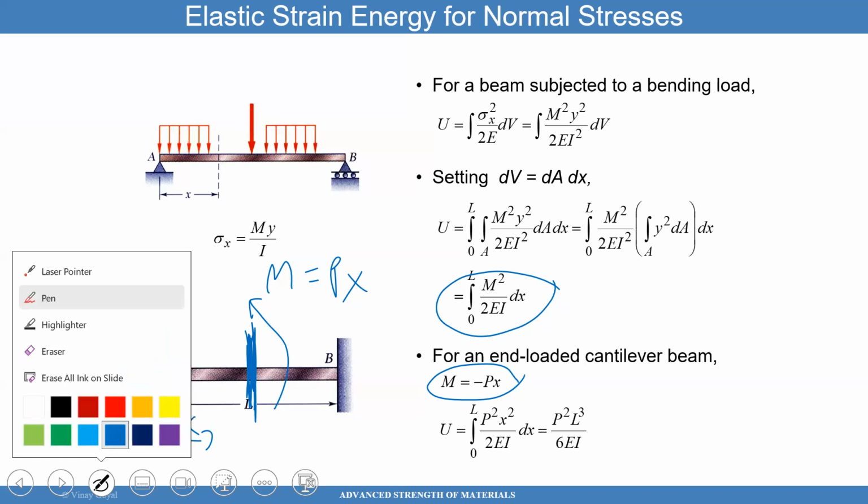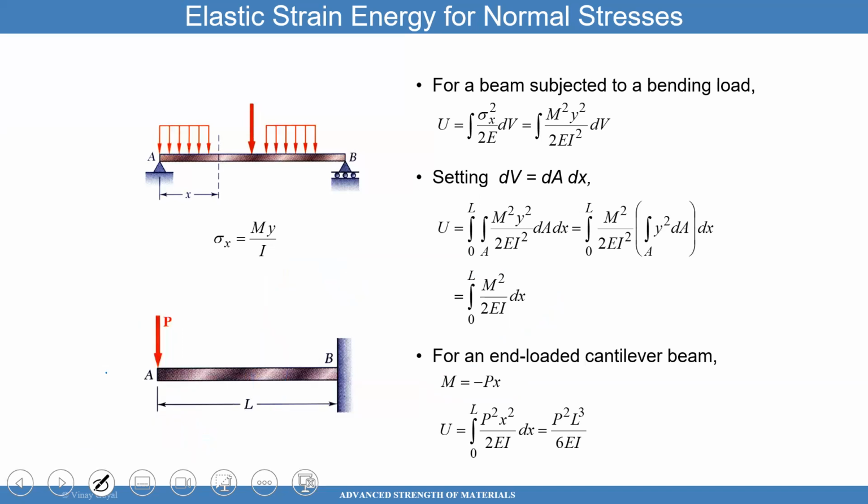And moreover, and I'll cover this later, but just for fun, this is equal. What is the work done by this load applied? 1/2, 20 points for you, kind of 10 points because it's really 1/2 in front. 1/2 P times the vertical deflection, correct? Didn't we cover that just a minute ago? We said that the work done can also be written in terms of load applied times the deflection divided by 2. That's the work done by that load, right? Does that make sense to you guys?